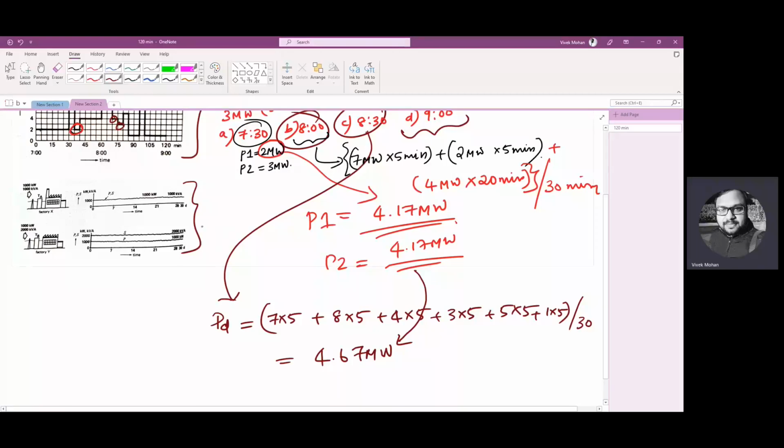This is unity, 100% power factor for X. So based on this, if we are going to find the electricity bill, the energy and demand being the same, the watt hour meters and demand meters will show the same reading at the end of the month, because this is for 30 days. They will show the same reading.